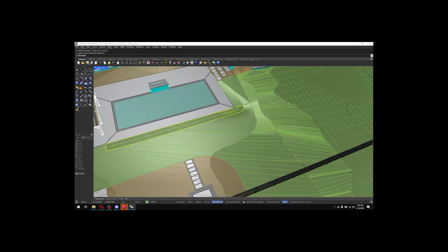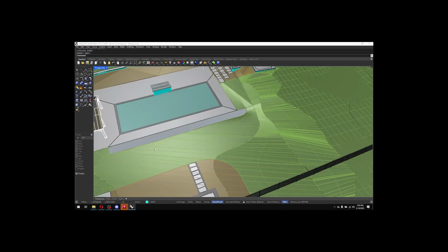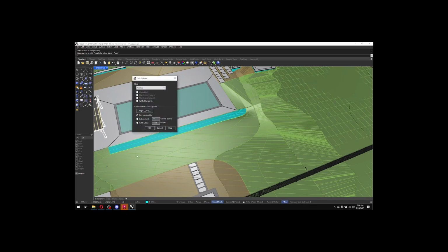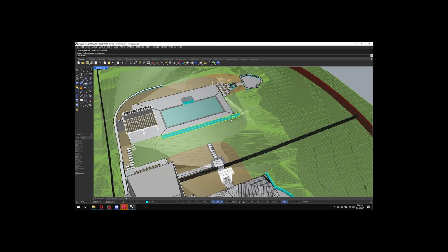So all this shape is a loft from that proposed contour line and this edge of the pool deck. And it makes that surface. So if I need really detailed grading, I use loft. That's why all these kind of look like weird stretched out shapes. They're not going to be stretched out when you go to render it. It's just how they present the ISO curves. So all this shape in here, that's all loft. Every single one of it's loft.